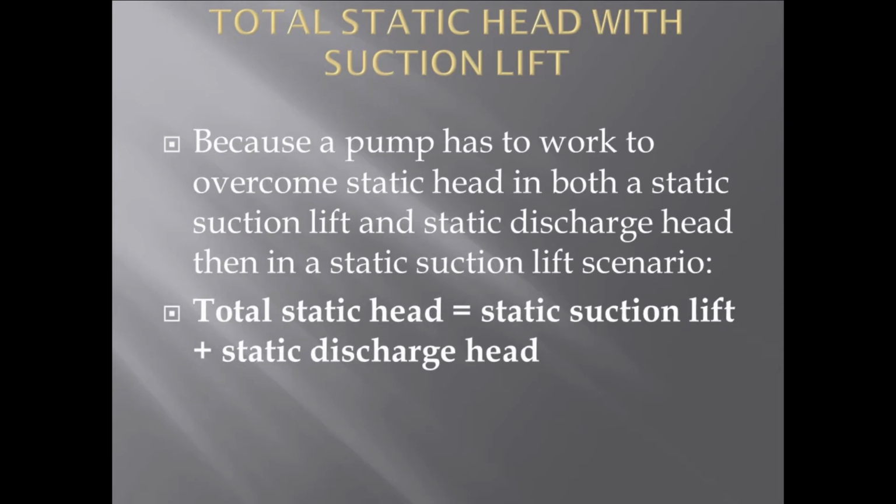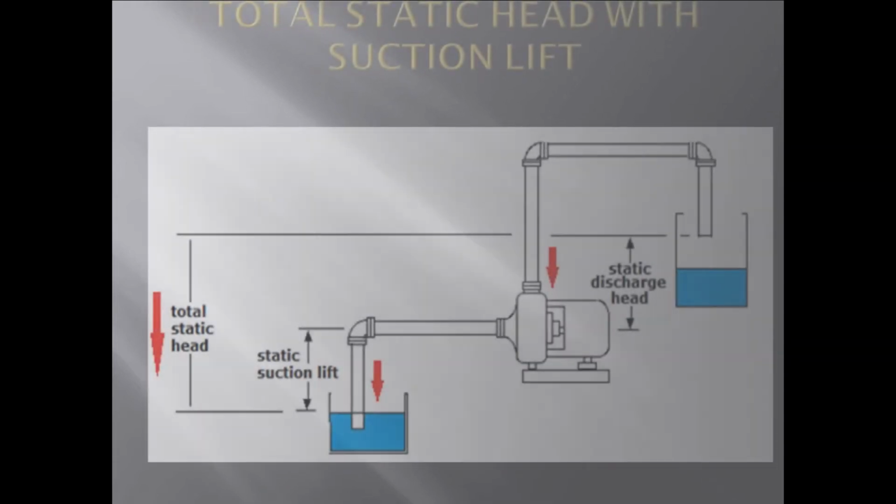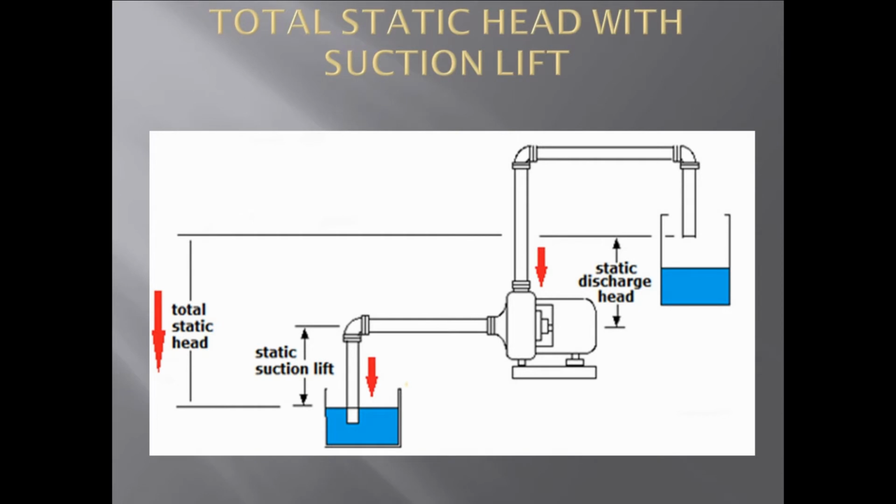Because a pump has to work to overcome static head in both a static suction lift and a static discharge head, then in a static suction lift scenario, total static head equals static suction lift plus static discharge head. In this situation here, we have a pump in a static suction lift situation, and we can see that the total static head is the sum of the static suction lift plus the static discharge head.